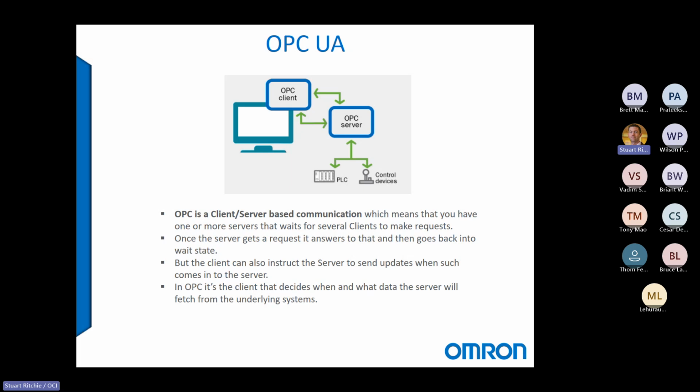So there are some implementations in OPC UA to assist with this. The PLC can actually let the client know when certain tags have a new value. So it can really clean up your network compared to Ethernet IP or Modbus. Great for SCADA applications. It's very good for cloud monitoring and SCADA.